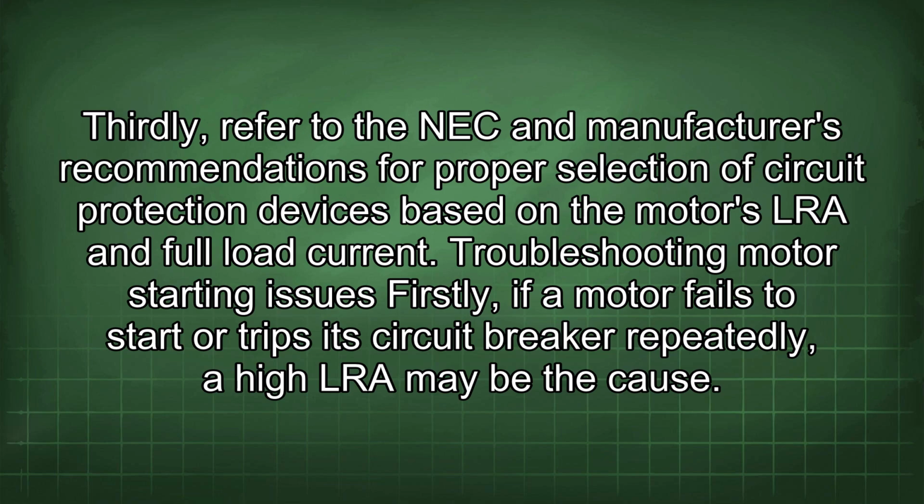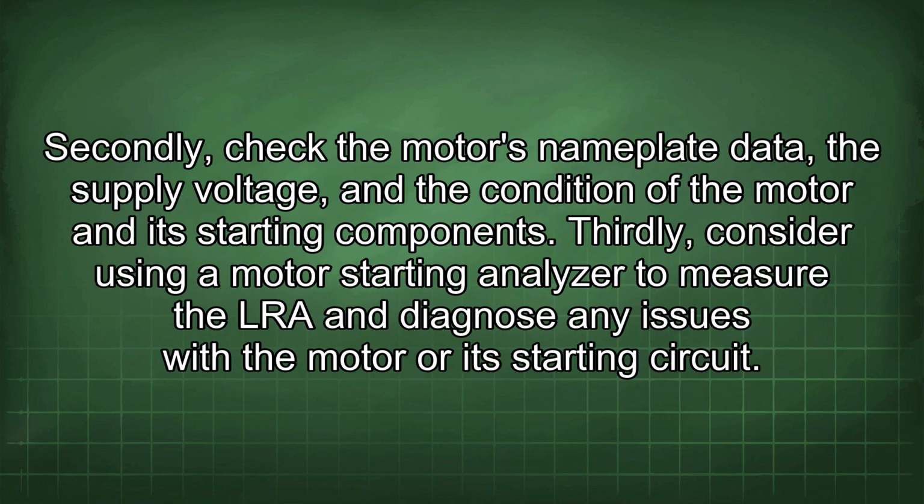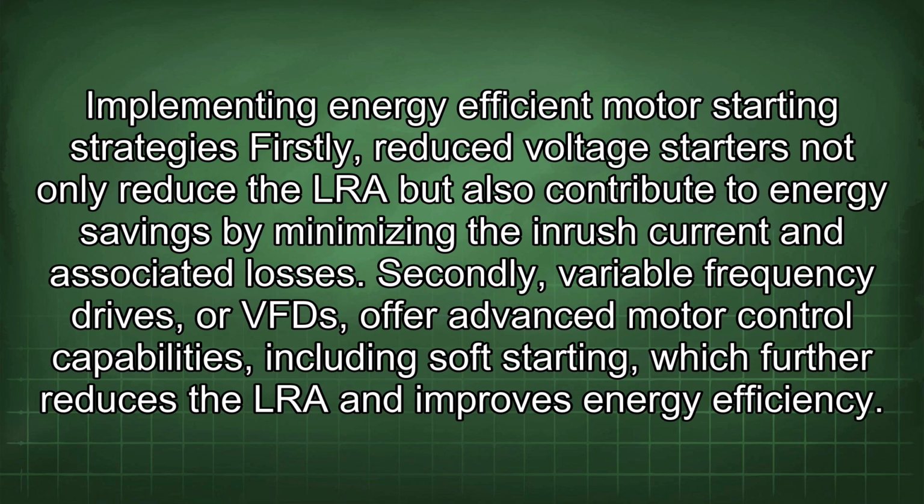Firstly, if a motor fails to start or trips its circuit breaker repeatedly, a high LRA may be the cause. Secondly, check the motor's nameplate data, the supply voltage, and the condition of the motor and its starting components. Thirdly, consider using a motor starting analyzer to measure the LRA and diagnose any issues with the motor or its starting circuit. Implementing energy-efficient motor starting strategies.